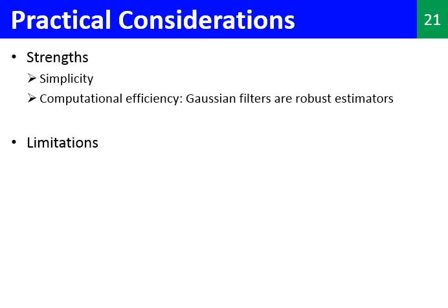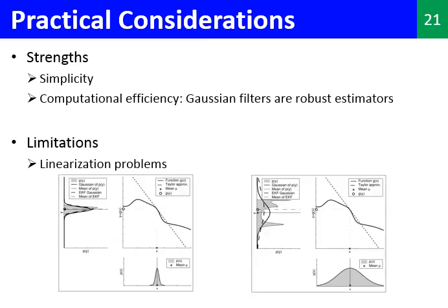So what are the limitations of extended Kalman filter? Can you think of any? Now, since we use linearization to formulate the EKF, there can be several associated problems. So one problem is the nature of the input random variable at each iteration. That is, if the variance of the random variable is too high, you can see in this figure what happens to the distribution of the resulting random variable.